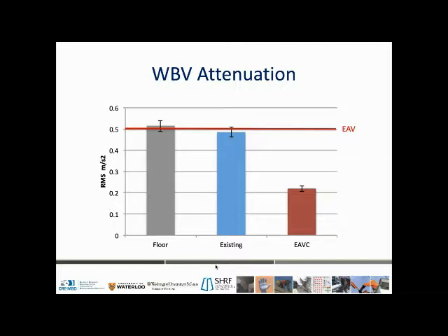These seats were able to reduce the floor vibration levels by about 8%, getting the vibration exposures just below the action value. And the vibration canceling seats shown here significantly reduced the floor exposure levels by about 55%. And this brings the exposure levels to about half of the action value. So we successfully manipulated whole body vibration in the field while controlling for individual differences, cab design, and the workplace culture. So let's see what it does to vigilance over the course of a workday now.